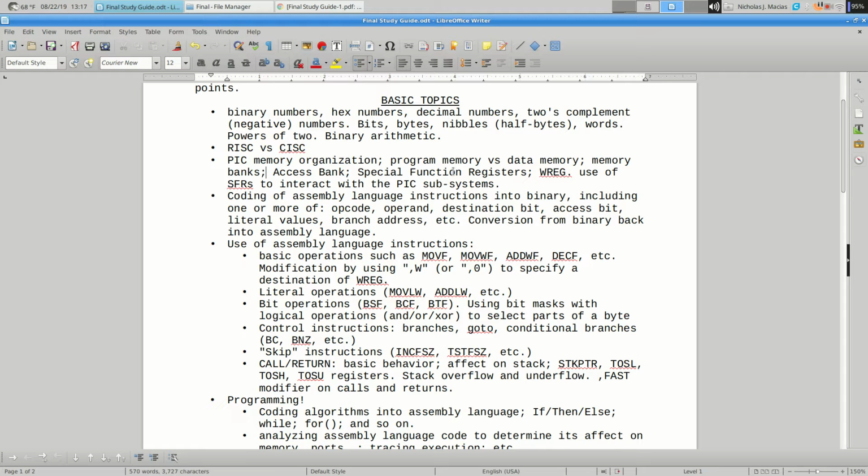So this access bit that we set to a 1 or a 0 says which 12-bit address we really want to access. Are we accessing a 12-bit address that begins with 0000 or begins with 1111? Because we can only specify 8 bits, if we want to access F80, we've got to somehow say the first 4 bits of that 12-bit number should be 1. We use the access bit for that.